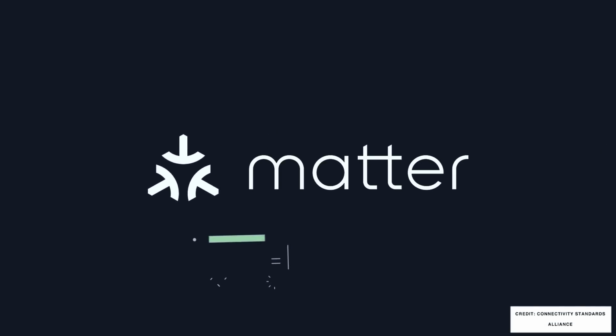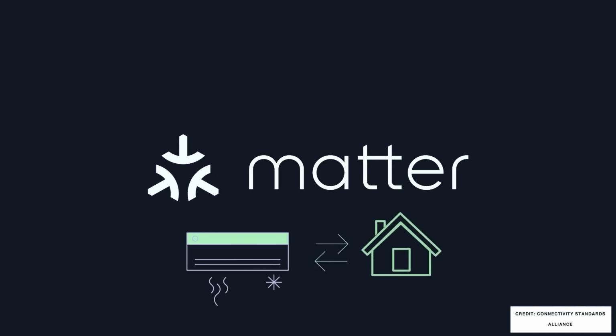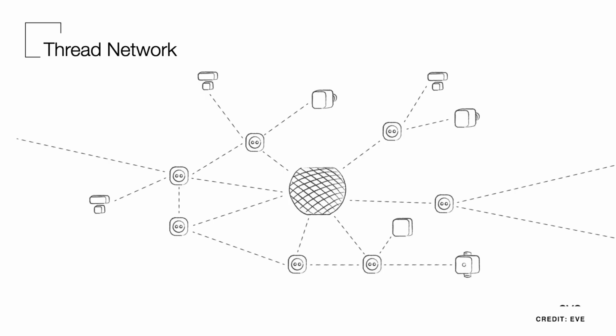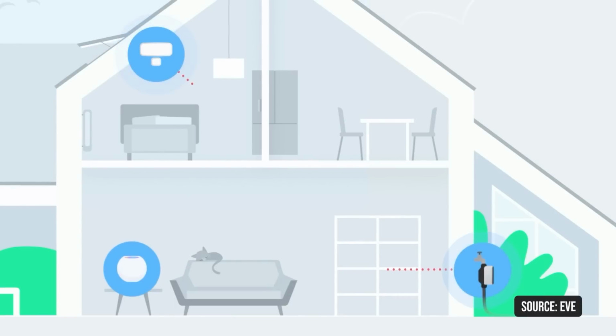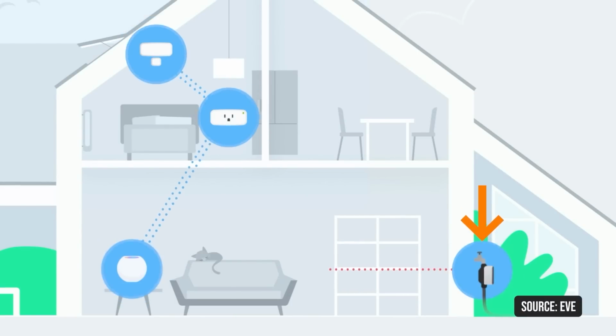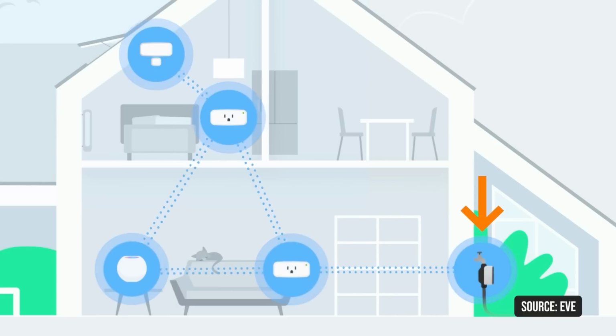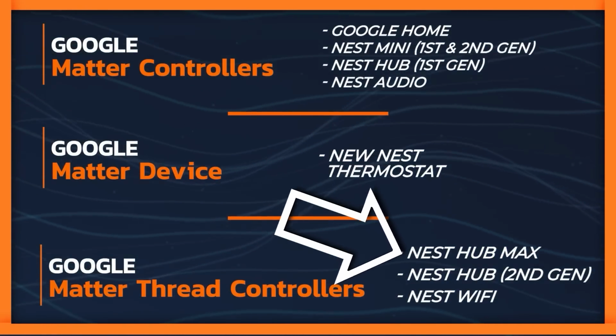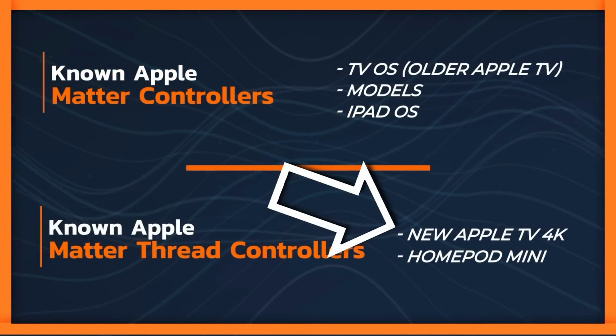But Thread is good for apartments for a few reasons. It has specific technology included in it that avoids interference from other Thread networks and from Wi-Fi. It's also going to be better and better as you build the Thread network in your home, because not only is it fairly long range, but it's also going to be able to use different paths to get to your smart lighting if one of them has gone offline. One thing to keep in mind is that you'll need a Thread border router to use Thread-based smart home products, which I do have a guide to, again, linked below.